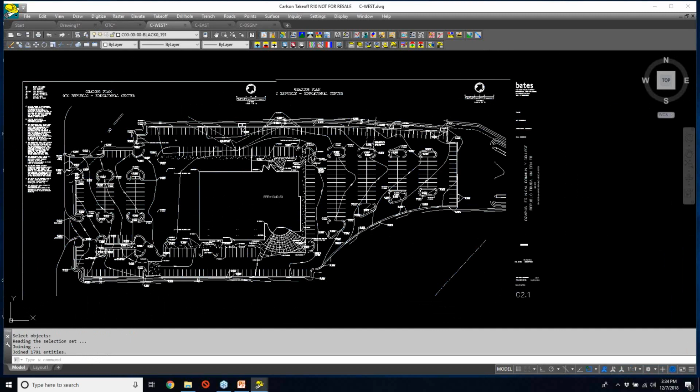And now when I take a look at this contour, you can see how it now does actually snake through, and it's continuous. Same thing here. This contour keeps on going through, and same thing with this one. So now when I do my assigning of contour elevations, multiple in series, I have many fewer contours that I have to pick through. So the Join Nearest is a big time saver when it comes to getting your work done, and can really make short work of getting all this data figured out.